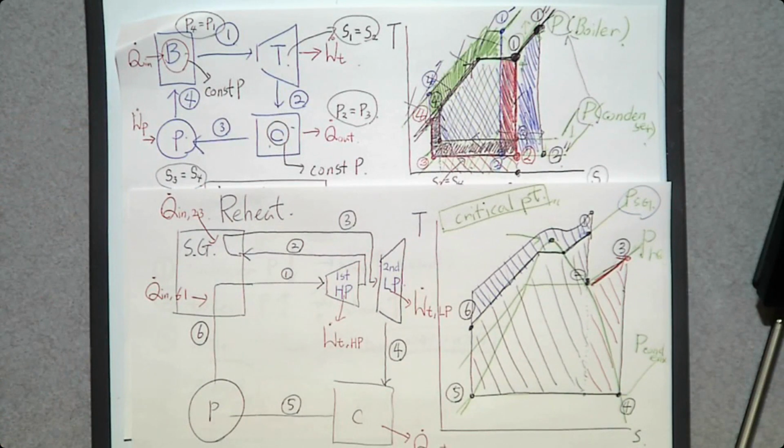So the standard Rankine cycle, decreasing condenser pressure, increasing boiler pressure, introducing steam generator, introducing reheat process, and supercritical steam. So those are 5 modifications.